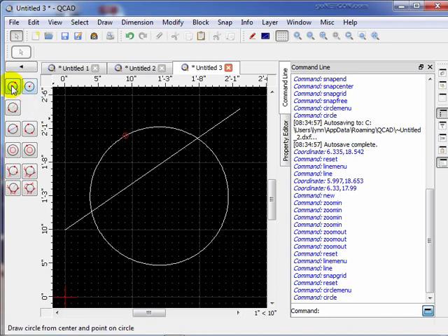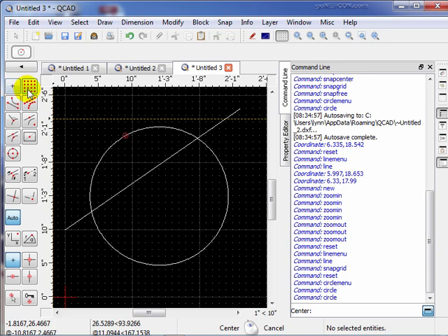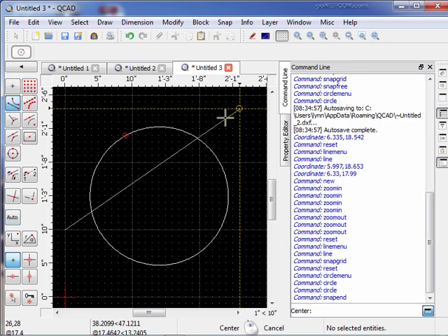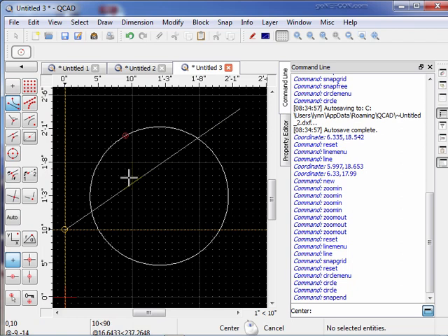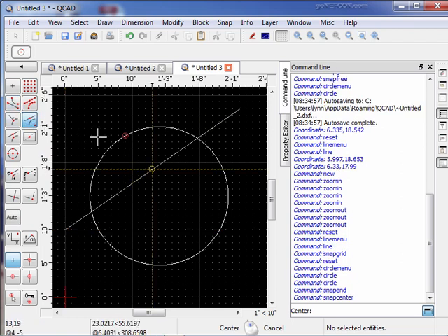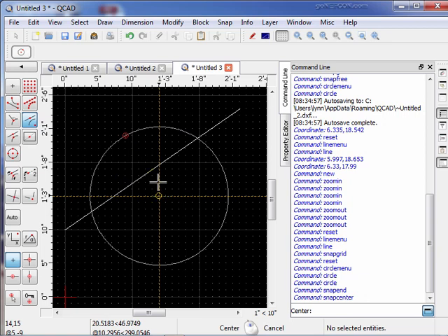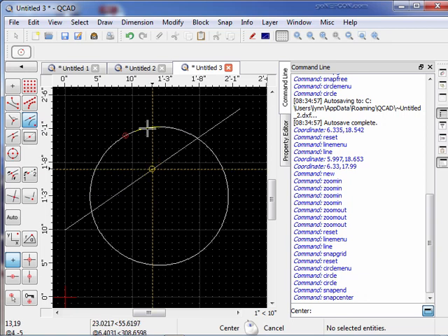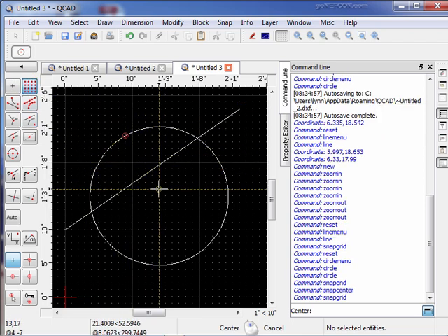Normally what I would do is snap it to something. I'd snap it to either the end of one of these pre-existing objects or the center of one of these pre-existing entities. I have a lot of trouble saying entity instead of object. Entity is a proper term because it can be a cluster of several different pieces. So an entity is the right way to name this process. Or we can have the circle center point start relative to one of the grid points.